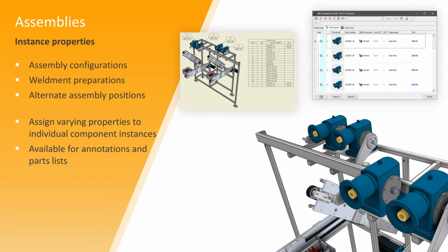So the level of detail option is no longer there, and you'll notice that in a little video that I'll play in a second. The master level of detail and all of those user-defined levels of detail, including any substitutes, are retained and converted to model states in the 2022 version. So when you migrate across, you will notice that change in your 2022 option.